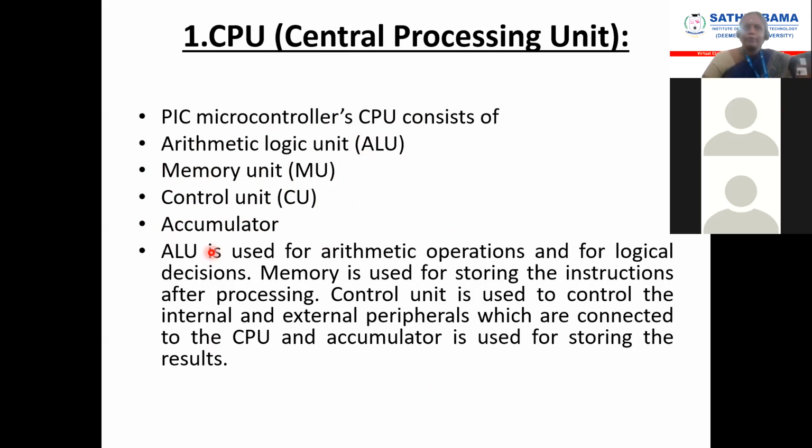Regarding the control unit, you always know there is the data bus and address bus. Along with that there are control signals; read and write are the two most important control signals, which are very important when I want to write or read data. The PIC microcontroller also consists of an arithmetic logical unit, which can do arithmetic and logical operations. Arithmetic operations are addition, subtraction, multiplication, division, increment, decrement; logical ones are NOT, AND, OR, exclusive OR, rotating and swapping instructions.